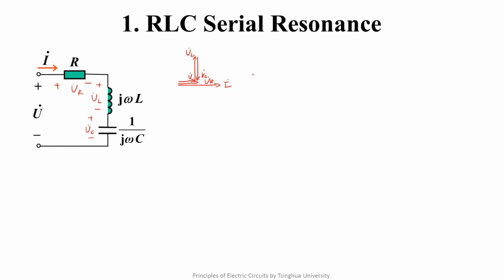In the last lecture, we've derived that the resonant condition of the one-port network is this. And the result is this. We've also derived that the input impedance of the port in resonance is a resistance. Now we discuss the voltage of the energy storage elements in resonance in detail.